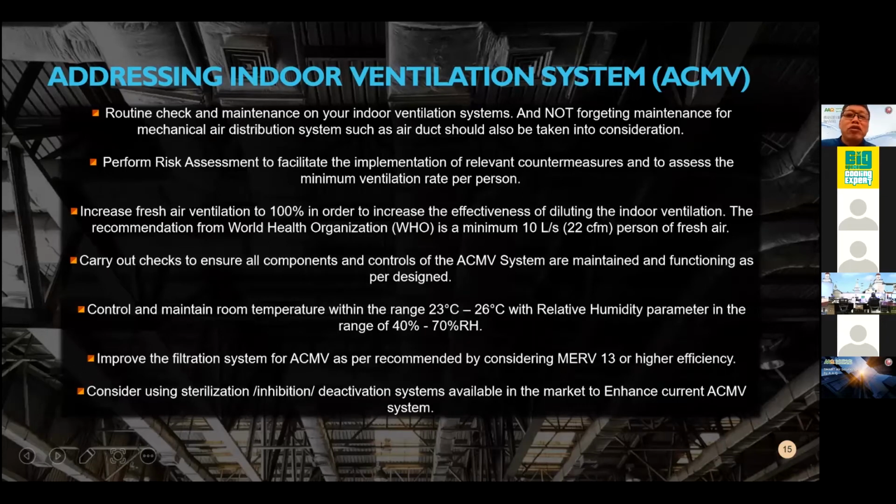Addressing indoor ventilation for ACMV. Normally I think the DOSH guideline gives you a very clear-cut routine check and maintenance on your ACMV, to make sure that it's fully functional, in good condition, at optimum performance. And not to forget, maintenance of mechanical air distribution or air ducts should be taken into consideration, because that is the most contaminated area as well.